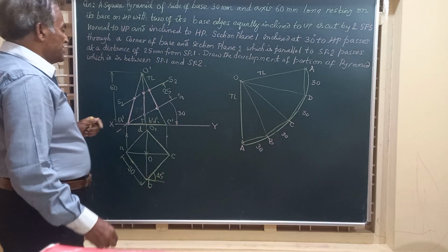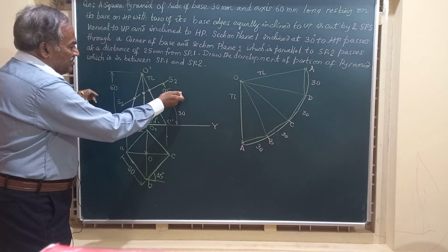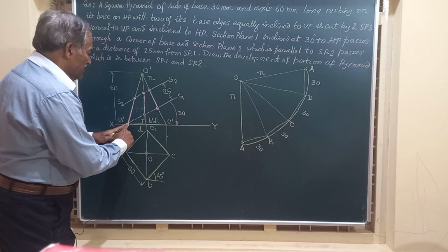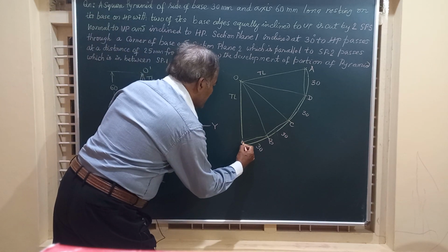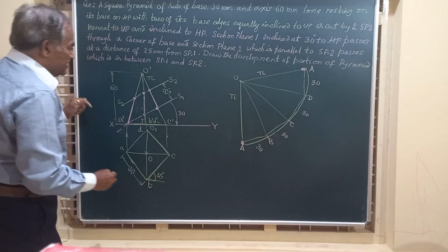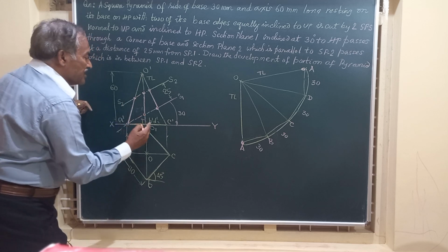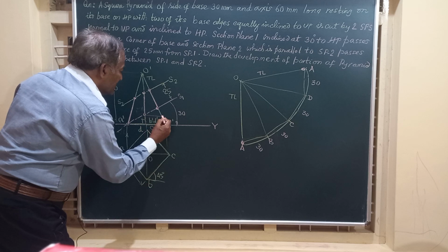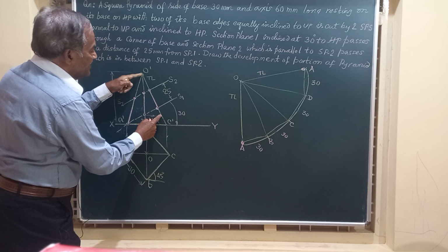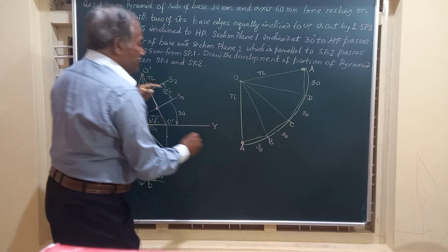And here, let us mark the points where the section plane is cutting the solid. Section plane 1 1: friends, it is passing through A of the base. So I am taking only the section plane 1 1. Then it is cutting vertical edges OB and OD here. It is not the true length, hence I shift that to the last line which is the true length and take this measurement on OB, OD.